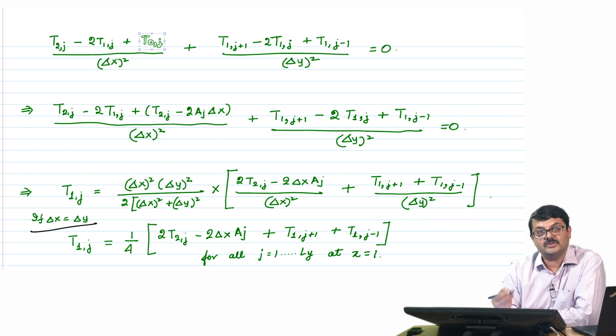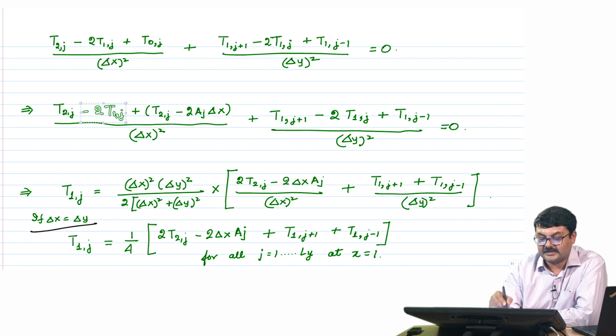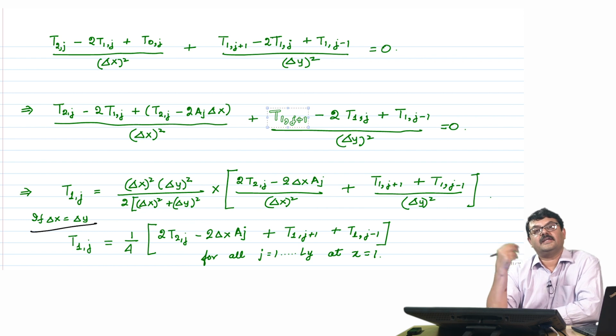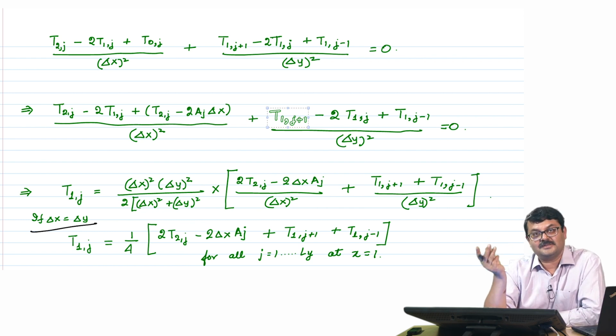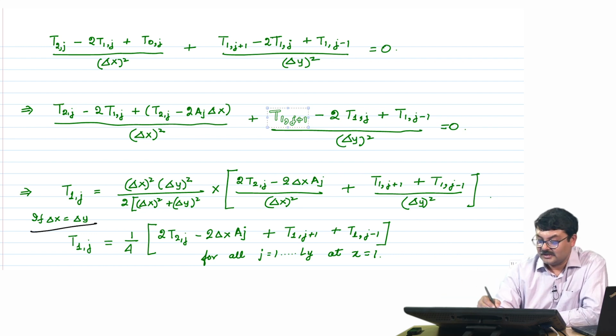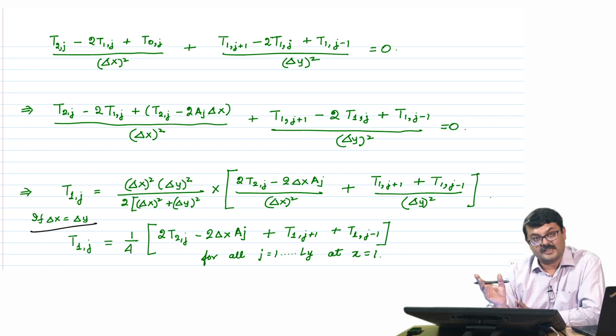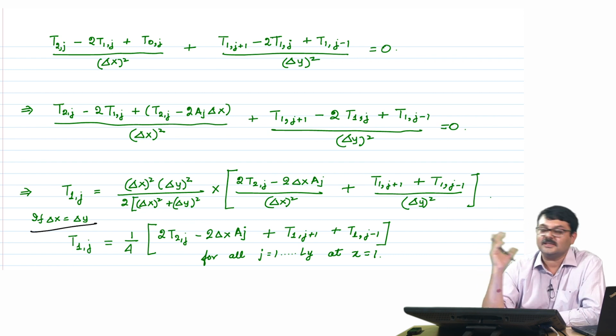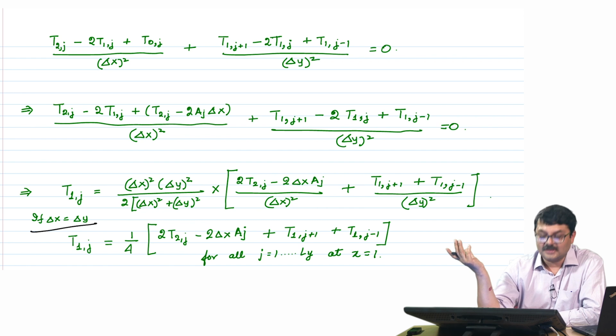I mean, at least you know at a particular iteration, and of course, iteratively the values of each of these points shall evolve, and when the value does not change while maintaining the boundary conditions, now in terms of dT/dx, or rather in terms of A j, then they basically become stationary, meaning they do not evolve within your tolerance factor, you say that you have got your answer.